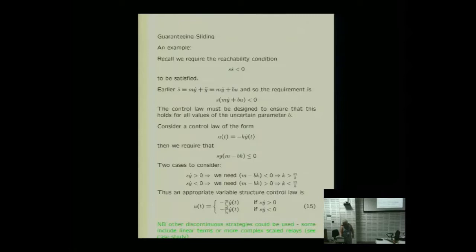there's going to be many, many control laws I can define. But the first thing we do is initially think of doing something which removes parts we know from this equation. And that's where people go wrong. They tend to do that with the equivalent control, and sometimes they're the same, but sometimes they're not. Okay? So here I'm applying something that looks very like the equivalent control, but effectively I'm applying it here because I want to simplify this reachability condition and get rid of parts I know.